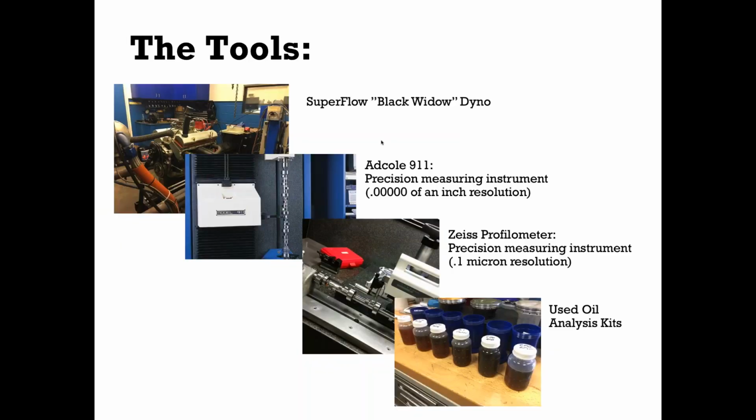The tools that I use the most, and now I'm going to transition a little bit into my oil experience: one, again, I can't thank the guys at Shaver enough for the help they provide us in being able to utilize the Black Widow dyno they have out there, which is a fantastic tool, very repeatable, very easy. It's automated, that way you take out the human factor.